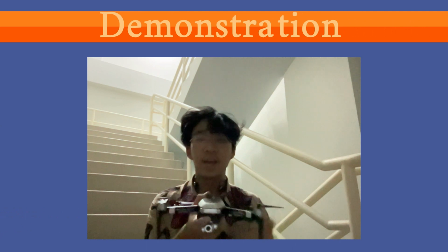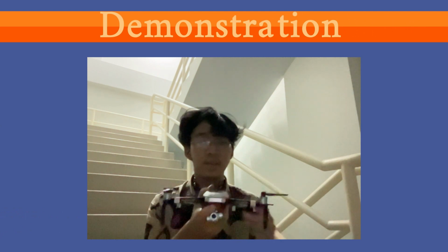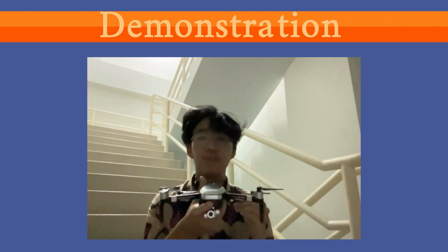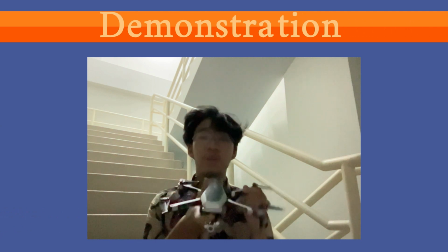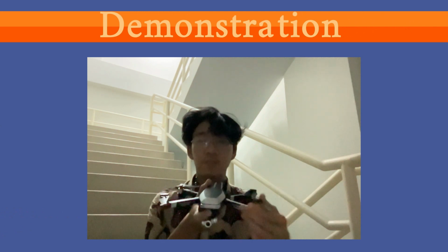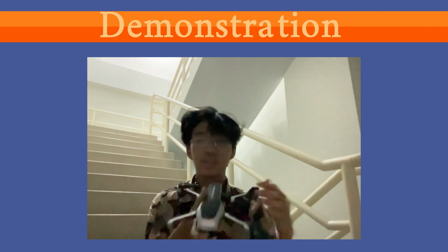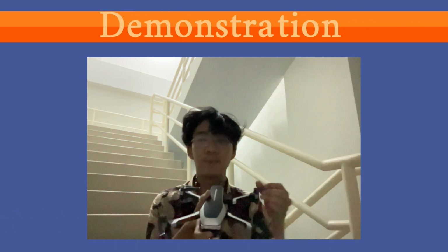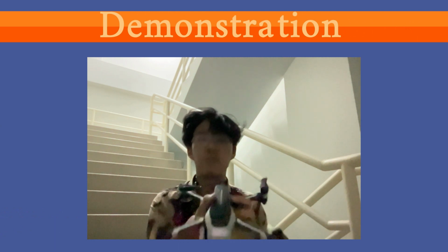speed. And if it, for example, wants to move forward, it needs to tilt the quadcopter forward. So to do that, it reduces the thrust of the forward rotors and increases the thrust of the backward rotors. This makes it move forward.